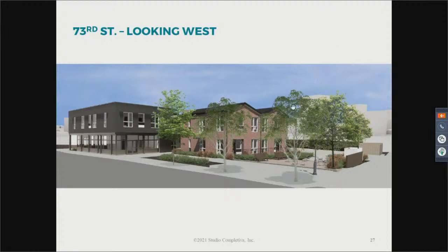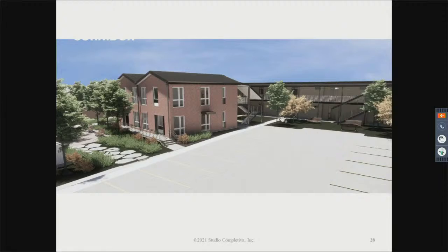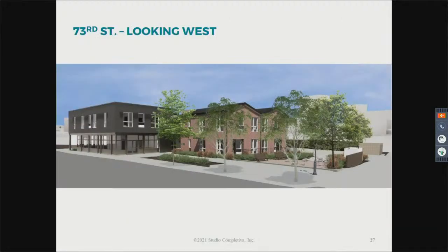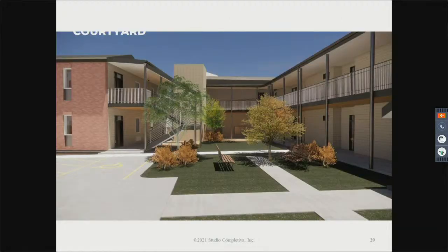Okay, and it's going to be all brick facade all the way around. The brick is going to be really the predominant material, and it's going to really reinforce the character of Lowell. And the brick will be used really on all the exterior sides. The only area where, to be cost effective, we're anticipating a transition from brick to a low maintenance cement fiberboard is just on the inside of the courtyard, as you see in this rendering.